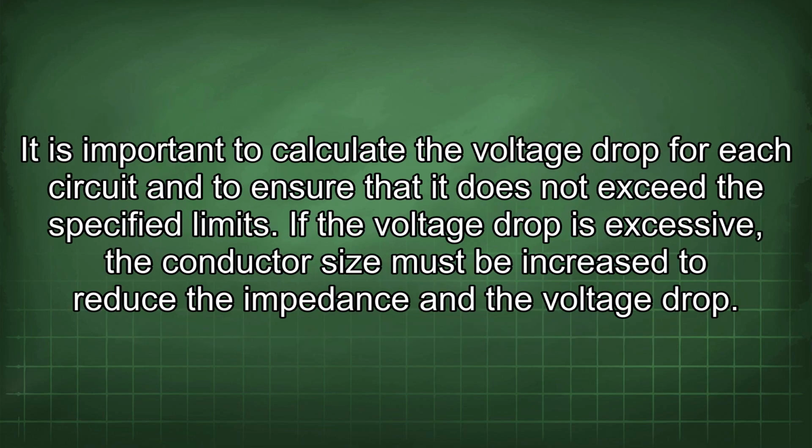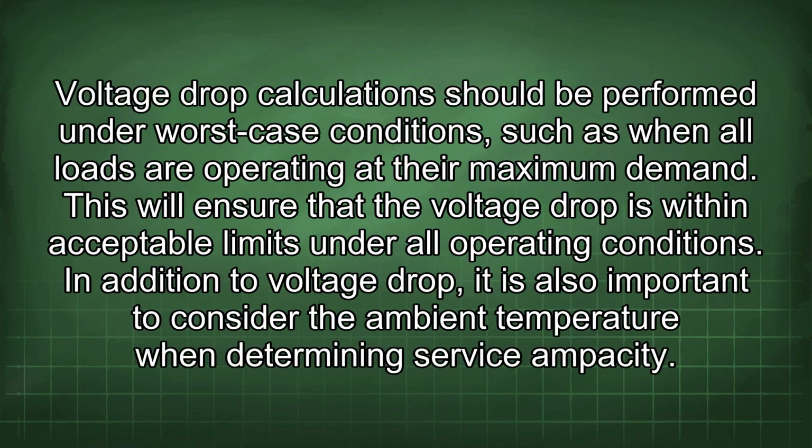It is important to calculate the voltage drop for each circuit and to ensure that it does not exceed the specified limits. If the voltage drop is excessive, the conductor size must be increased to reduce the impedance and the voltage drop. Voltage drop calculations should be performed under worst-case conditions, such as when all loads are operating at their maximum demand. This will ensure that the voltage drop is within acceptable limits under all operating conditions.